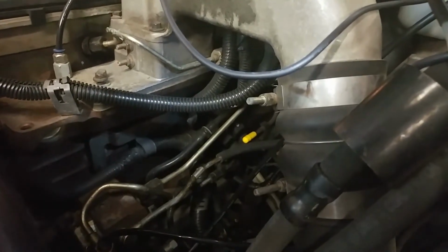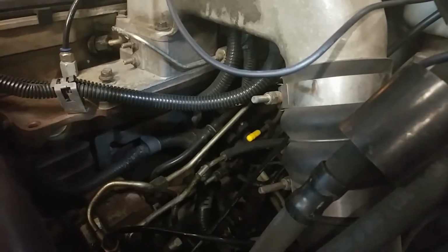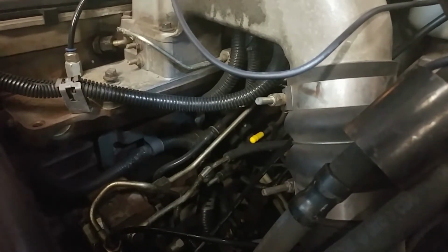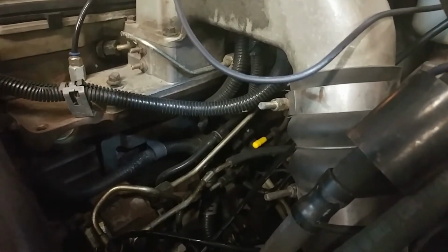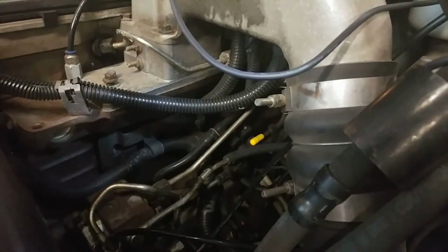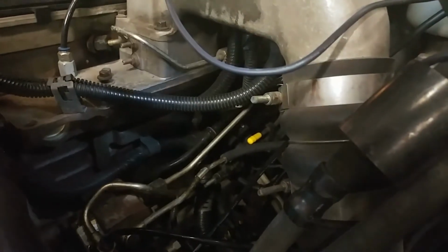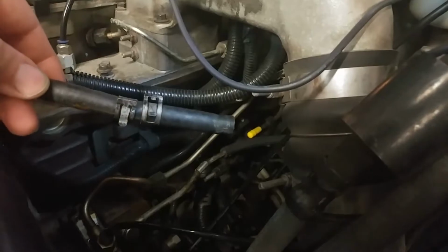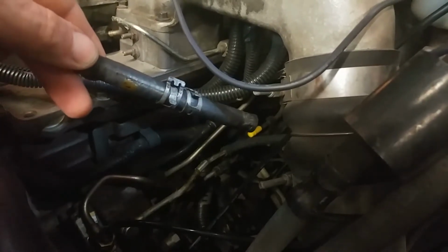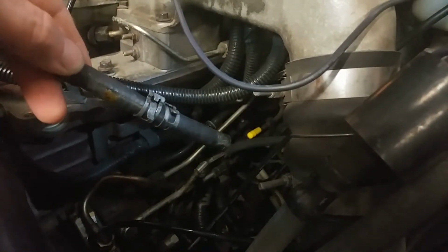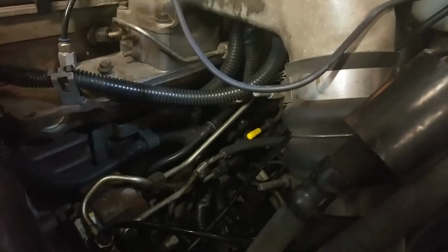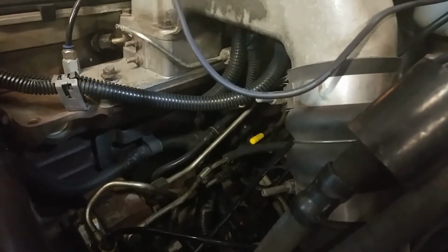We want to show you the connection that is made from the CP3 pump back to our Y connection, so we can either measure the flow from the CP3 or plumb it into the Y and return it back to the tank. We have a short section of rubber hose here that's been removed between this shallow cap and this metal hard line, where we've slid this rubber hose up on here.